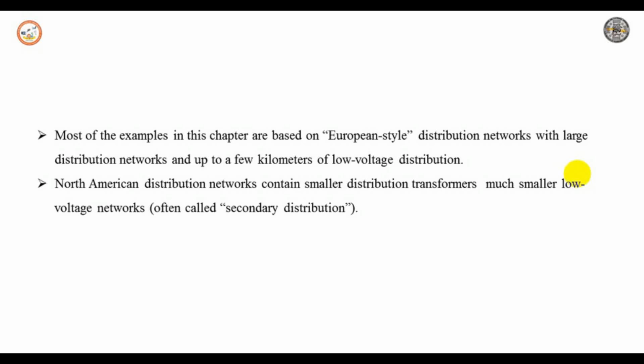The primary source of voltage unbalance of less than 2% is single phase loads on a three-phase circuit. The voltage unbalance can also result in blown fuses in single phase or three-phase capacitor banks. A severe voltage unbalance can result in a single phasing condition. A voltage unbalance is considered severe whenever the percentage is greater than 5%.